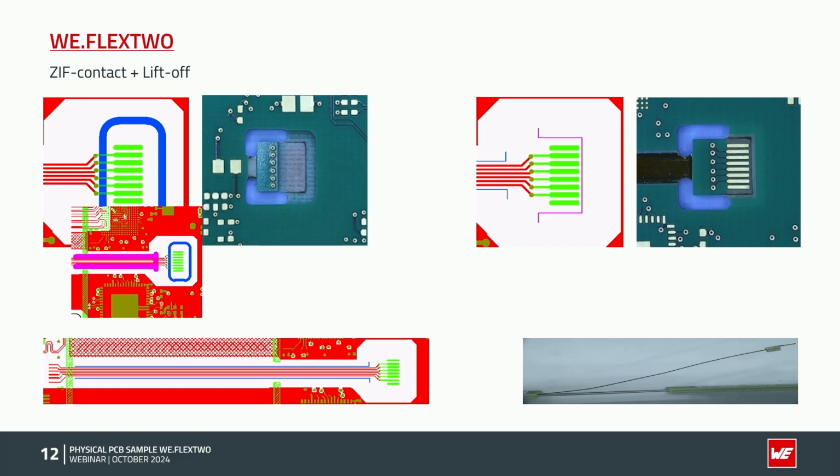So if you can shift the connector from the inner layer to the outer layer by using these plated through holes, we don't have this problem. And of course, we have nearly a standard process. We do this depth milling in the final step of the contour routing, in the same step.